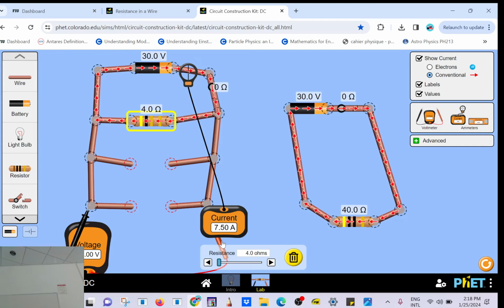So remember last time we talked about internal resistance? So I'm going to measure the EMF. EMF meaning what's the voltage across the power supply when no load is connected. So you have that. I'm going to measure it here. And it says, do you see? It's about like 4.5, about 4.5, right?